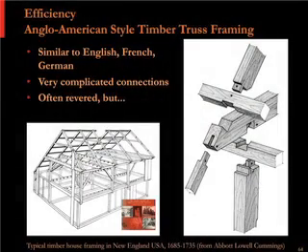And the concrete is actually doing remarkably well from what we could see. We didn't get to do any invasive testing or cores on that building, but there are really no signs of distress or spalling that we could see. And what they did there is just like the Romans did. They covered that with a stucco finish coat. So since day one, that's always been protected by stucco, and then the stucco's always been painted. So they had a layer of protection on there.